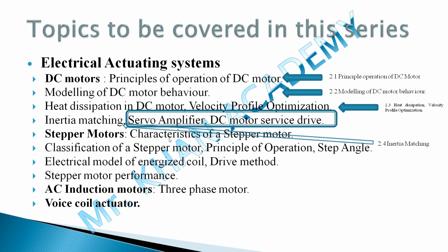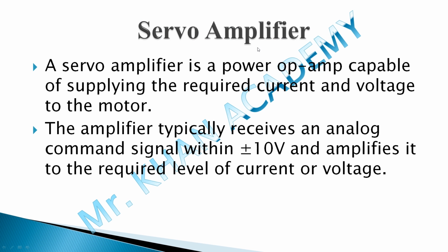Okay, let's start with the servo amplifier. The first bit, what exactly is a servo amplifier? Servo amplifier is a power op-amp, operational amplifier, capable of supplying the required current and voltage to the motor. What exactly is the meaning? Suppose I want to control the motor, like its direction and torque. In that case I need to vary the current and voltage, and my supply voltage is constant, and it might not be as per the requirement or specification of my motor.